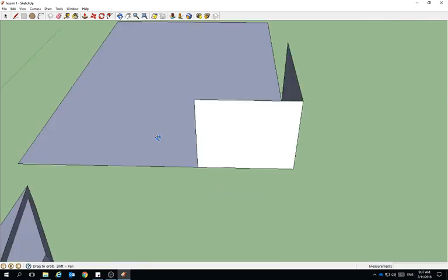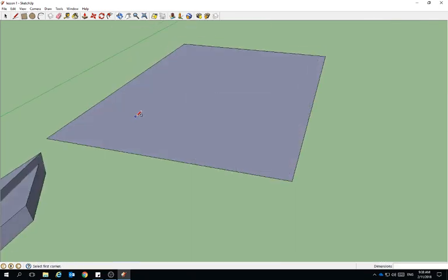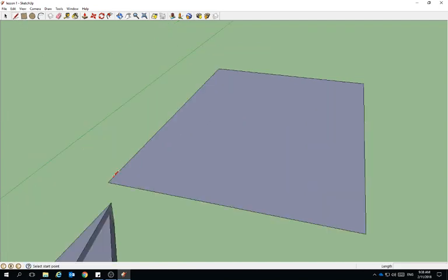So there's a nice easy solution for this. So I'm going to undo those two walls I've created using Control Z. And I'm going to use my pen tool, and I'm going to go around the edges. And again, this is going to be pretty quick and rough, but you'll get the idea of what I'm doing soon, where I am essentially modeling my rooms by going around and drawing the walls in one go. Alright, so this is going to be a very, very simple house, almost like a shed. I go to the end here.